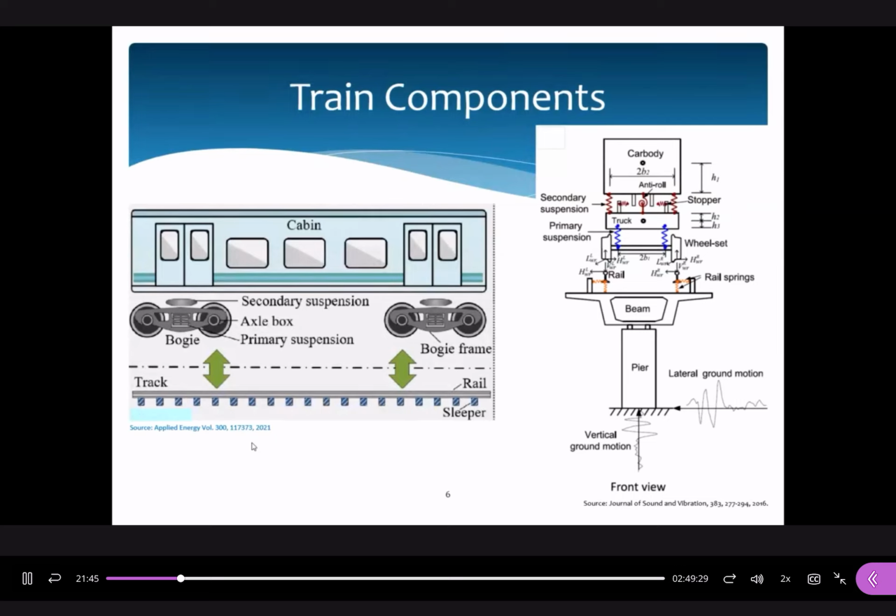Okay, the first suspension system we call the primary suspension. The primary suspension is to connect the track and the wheels, and the second suspension system is to connect this bogie to the supporting body. So normally we have two suspension systems. You may regard both of them as spring structures to absorb vibration energy. How to design and how to select appropriate spring systems we will talk about later in the coming 3 lectures. And below this we have a track, and this is a rail.